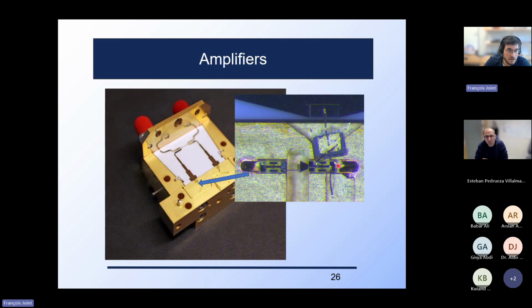How do you integrate this chip with the outside world? We need to use PCBs and wire bonding. We need to use soldering, and all of those introduce losses, and that's the challenge. So I'm looking for people with ideas to tell me how we can integrate that cleanly, so I can remove all these interfaces. I don't want wire bonds because they induce inductance and losses. I don't want soldering because solder has losses, and we talk about very faint signal. So that's the challenge, integration.